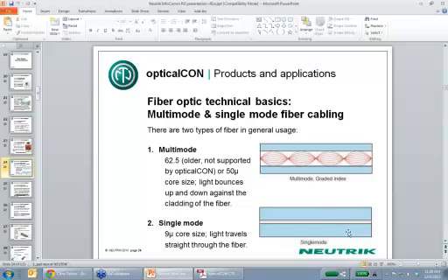It's shining directly through like a bullet. And this is the reason why single mode has 10 times the distance as multimode. It's a much more efficient way to be able to move that light from point A to point B without the kind of losses that are involved in the light dispersing and having to sort of bounce around the glass.